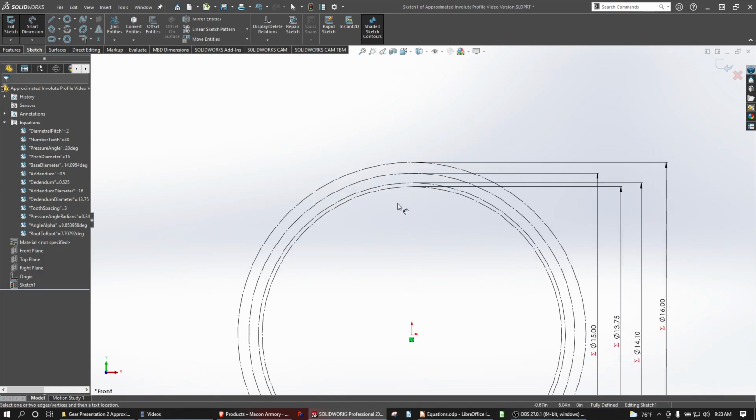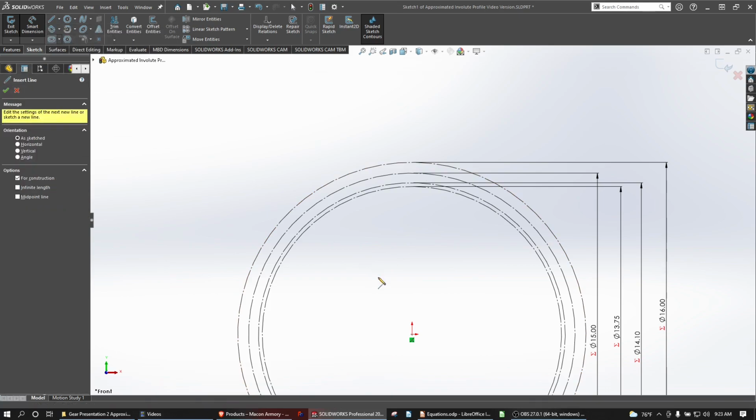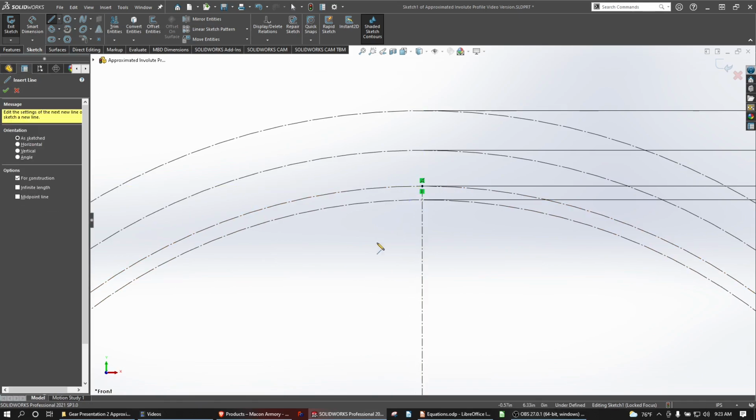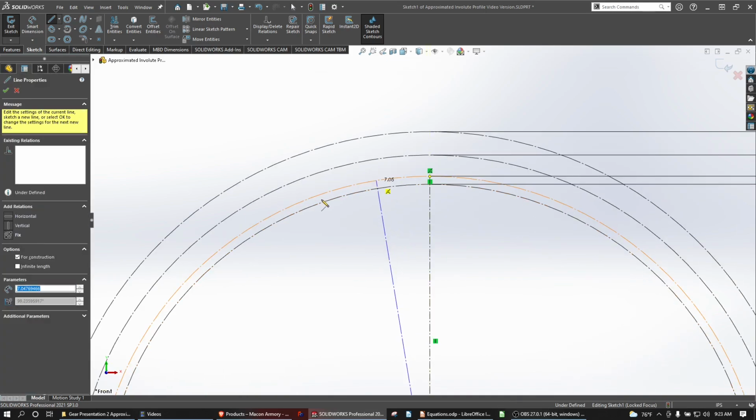And this time I'm going to start an involute tooth from the base diameter, and it will be tangent to vertical, and we're going to move out this way. Whereas our equation-driven curve put it down here before. Not a big deal. To start that, I'll draw a center line from my origin to my base diameter. And I'm going to mark out an angle here.